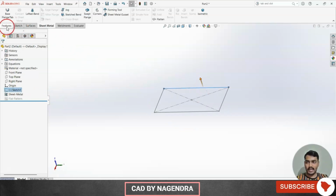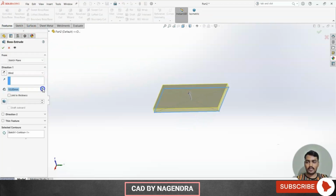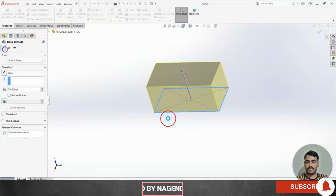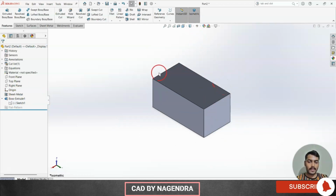So this rectangle, I am not using sheet metal. I am using features, part design. So just we'll create one block like this. Now this is not a sheet metal part. This is part design, right? So this part design we need to convert into sheet metal.